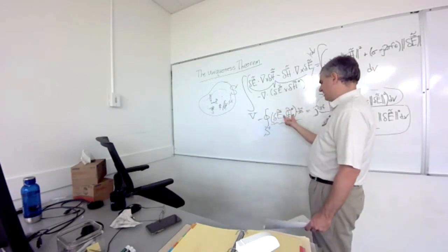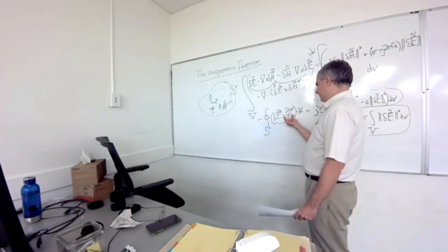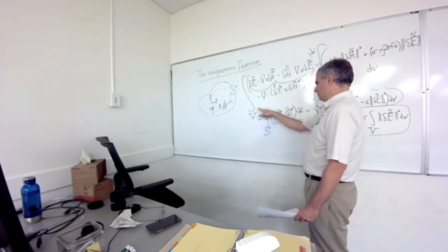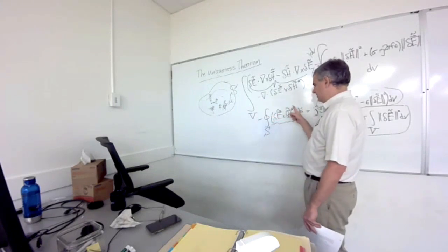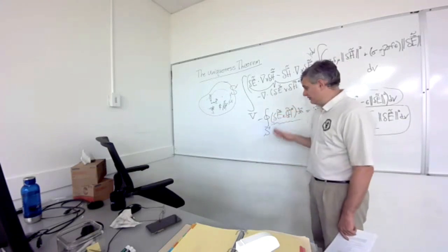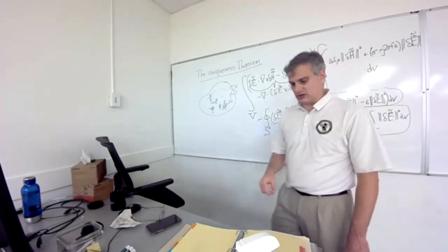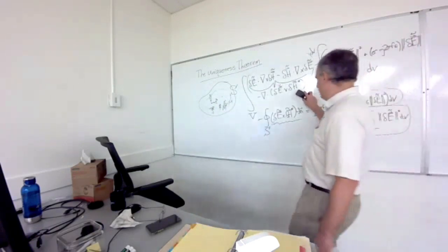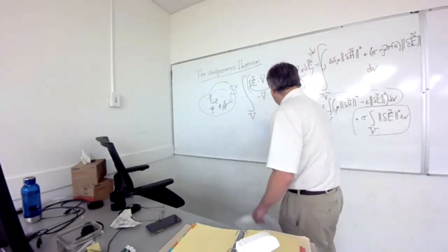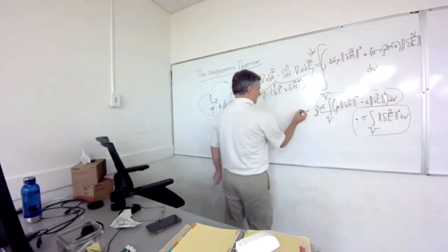The reason is, if I've specified delta H, then delta H is going to be 0. Or if I've specified delta E on the surface, then this part is going to be 0. So if one of these is specified, then 0 cross anything else is going to be the 0 vector. And if I integrate it across the surface, I get 0. So if you know the boundary of either E or H, this is going to be equal to 0.